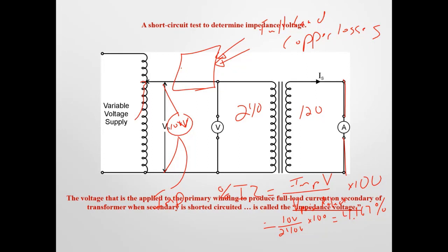But if I have a really bad fault current, will that overcurrent device do its job? Okay, so they have different ratings they are tested at that will successfully do its job and open up the circuit. So it's called interrupting capacity, and that's why it's important that we can determine, using percent impedance and the VA of the transformer, its maximum short circuit current.